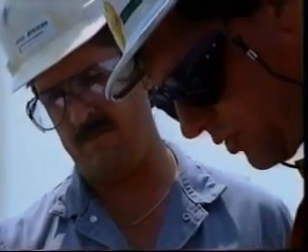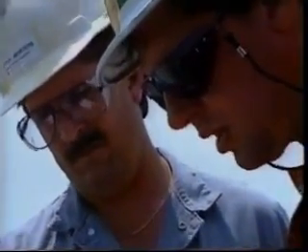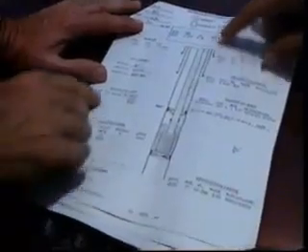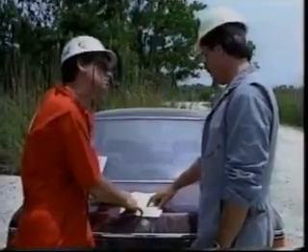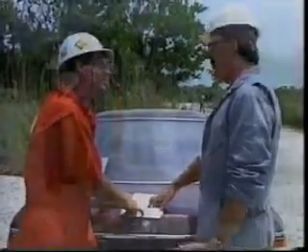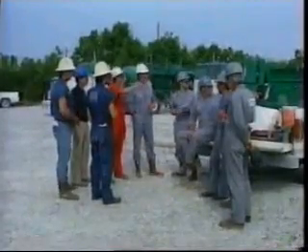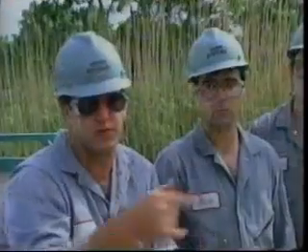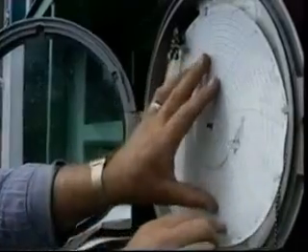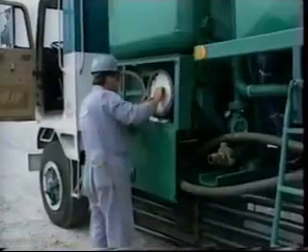After confirming the acid strength and additives, the engineer should review the well-bore diagram with the service company personnel. Everyone, including service rig personnel, should be made aware of the maximum surface treating pressure and the pumping time. A pin recorder documents treating pressure and time throughout the job.